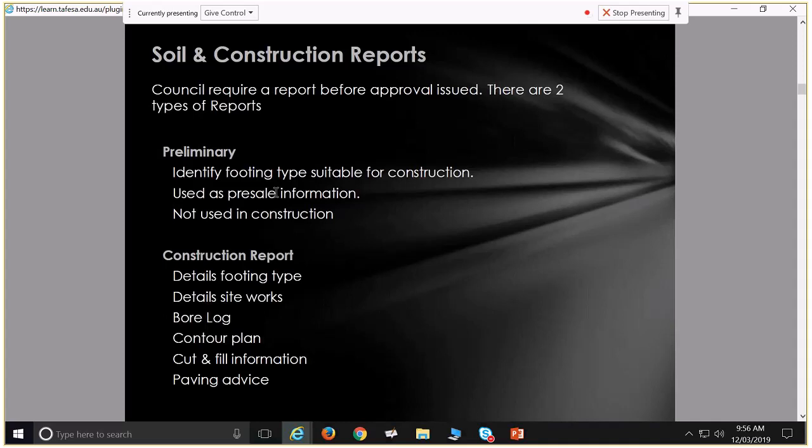So your paving starts here at the edge of your building. By the time it gets 1 metre out, it has to be 50 millimetres lower. That's for high rainfall areas. So that's for areas that have a rainfall intensity of 125 or above. In Adelaide, our rainfall intensity is 124 millimetres. So we're just sneaking into that lower requirement of needing 25 millimetres of fall for your first metre.